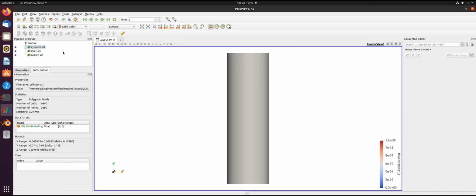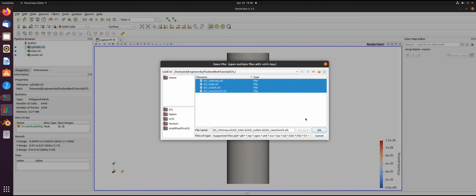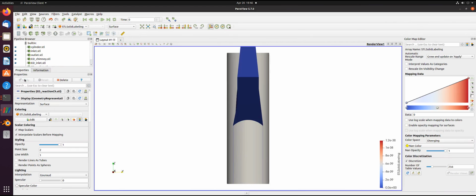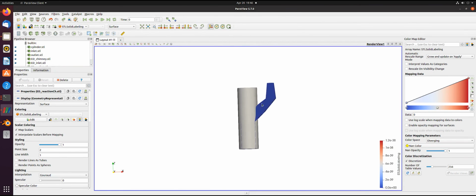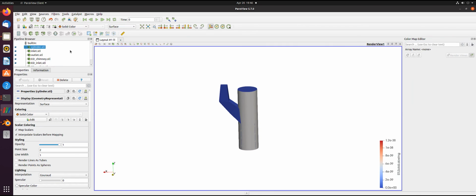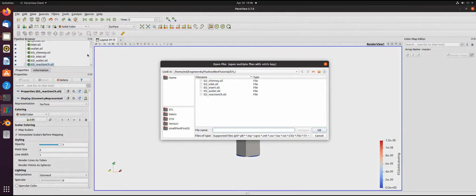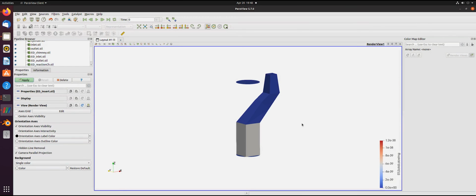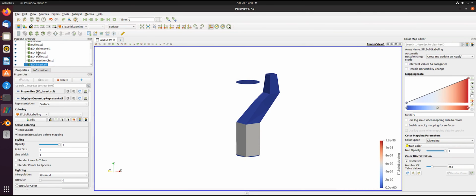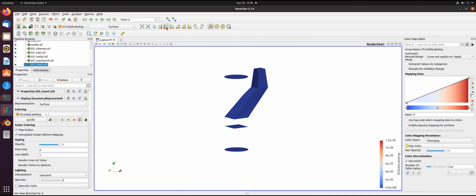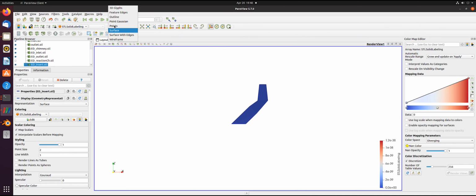In ParaView, it is possible to compare the old and new structures to each other. I deliberately did not change too much, so that the changes are transparent. After opening the main file, you can see that the total dimensions have changed a bit. The new structure is a bit larger in Z direction and probably 2 times as large in X direction. If I make the old cylinder invisible, it's getting clear that the rectangular reaction chamber is in the middle of the old cylinder. The particle insertion plane is roughly at 1/3 of the height of the top of the reaction chamber. It's visible in the side view after I switch from surface to surface and edge view.